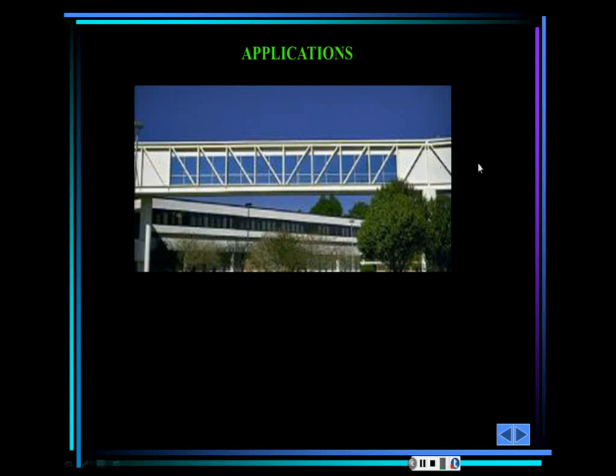Now imagine that you have this truss, and for whatever circumstance you only want to revise or review this particular bar here. If we apply the method of the joints, that means that I have to go either to this end or to this end, find the first joint with two unknown bars, calculate the reactions if I need to, and then I start moving from this joint to this joint to this to this, up until I reach this joint, which is the bar that I want to calculate. Can I do that? Yes, definitely I can do that.